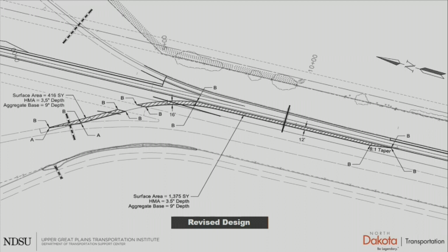This next example is a temporary ramp connection with the revised design standards, and we'd be looking at something roughly 1,400 feet long instead of 1,900. It'll consist of that 600-foot acceleration lane using an 8-to-1 taper at the end for an entrance ramp, or for an exit ramp, it would be a shorter 340-foot deceleration lane with a 15-to-1 taper. But both ramps in this situation use 16 feet of pavement instead of 24. So it's about 75% of the length, roughly 2/3 of the width, and then just a smaller ramp footprint and less impacts overall.